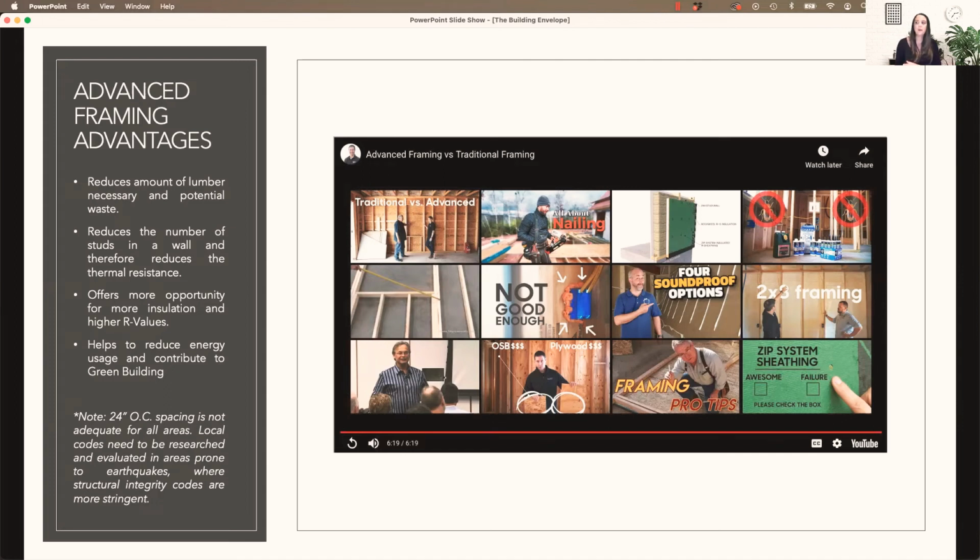He also talked about OSB, which is oriented strand board, which is similar to plywood, but just not quite as strong as plywood. And so OSB is typically used a lot in residential for exterior sheathing. That goes and protects the insulating factor. But plywood can also be used, again, like he was saying, it's just a cost issue at times.